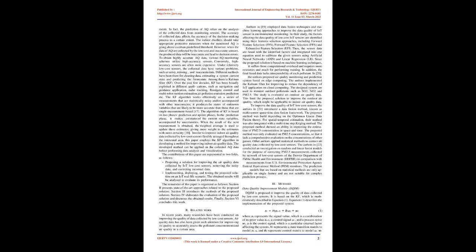These pollutant sources can cause health issues, discomfort, or lead to death in some serious situations. Here, some examples are given. The level of CO2 can be used to specify the exchange rate of air. A high level of CO2 indicates a higher level of contaminants owing to a lack of fresh air circulation.